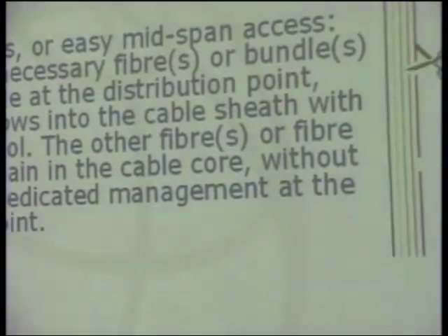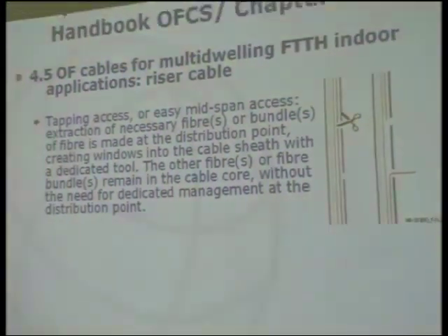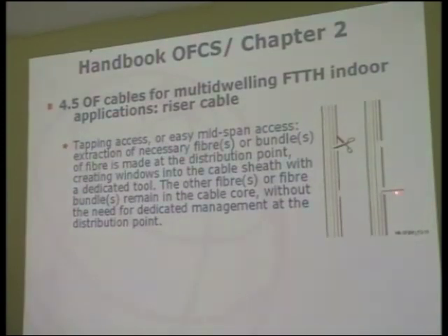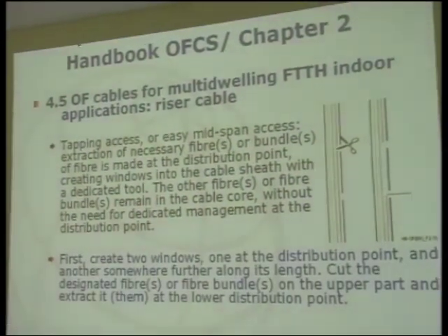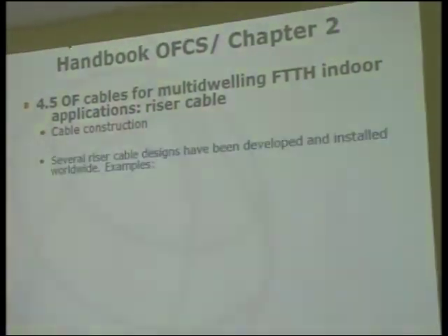So that's one of the applications being developed particularly for this kind of riser cable. And of course you can repeat it for the next higher floors for the remaining fibers in the cable. So this is a very easy way of installing. In some cases you can even use the same fiber without additional splices. You can reduce the number of splices if this fiber can go directly to the next user. Okay, this is the clarification.